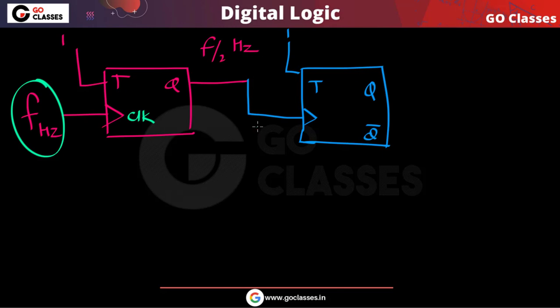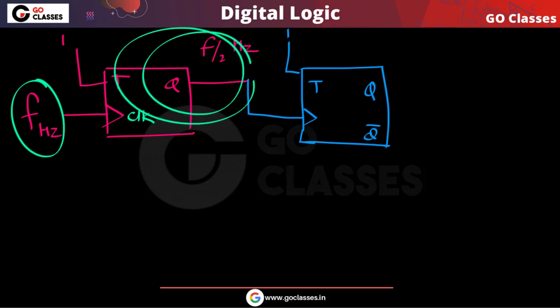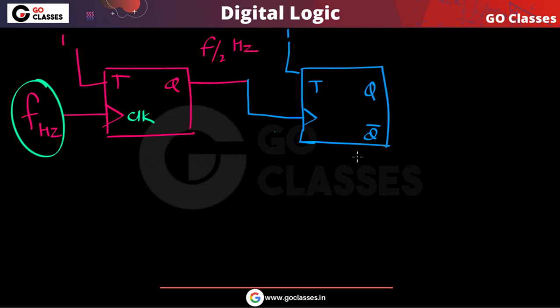Now this pulse you pass through another T flip-flop. So what will you get? The output of this flip-flop we are giving as a clock to the next flip-flop. Now this is the clock, and this output will have this frequency divided by 2, f by 2 divided by 2, so that means f by 4. So this now has frequency f by 4 hertz. Like this you can do.